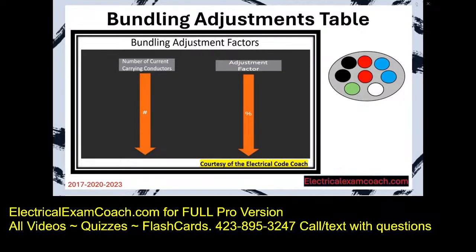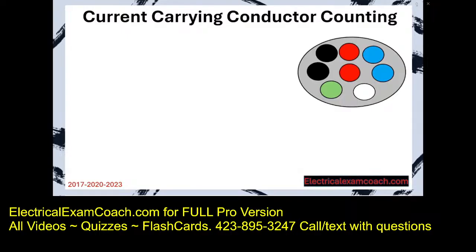Is it considered a current carrying conductor? What about grounding conductors? Are they considered current carrying conductors? Well, let's learn how to count conductors now. Now let's learn about current carrying conductor counting, because we're only going to be counting the current carrying conductors. You may get a question on your exam that gives you the number of conductors. That's easy. You're going to go to the tables and do the math.